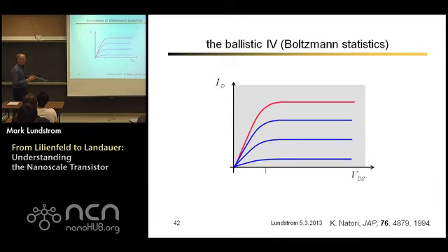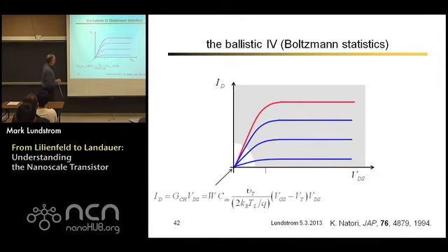Okay, so you plot the IV characteristics. Back when people first started looking at this, it surprised an awful lot of people. You know, it's a ballistic MOSFET, this is just some different kind of thing. You plot the IV characteristics, it looks like any MOSFET. The reason it does is the shape of the IV characteristics comes from pushing those energy barriers up and down. Just the magnitude of the current changes, that's all. So the IV characteristics look the same.